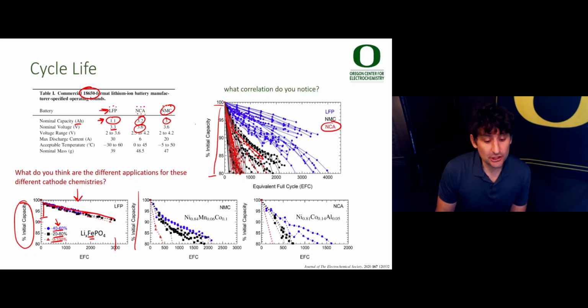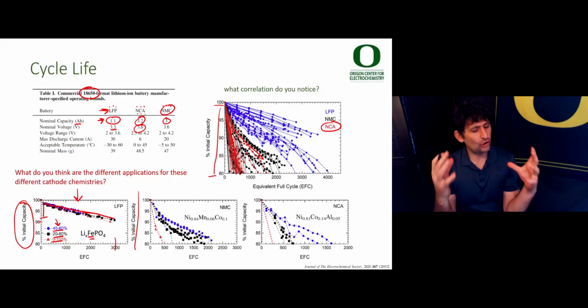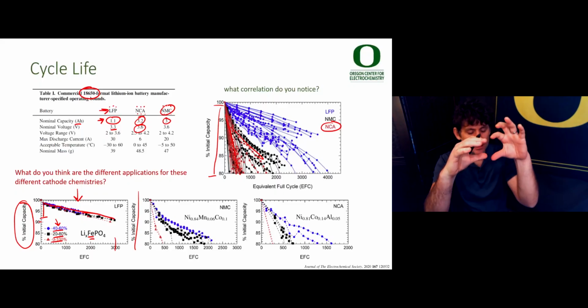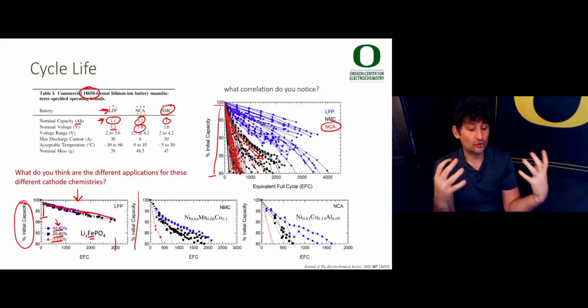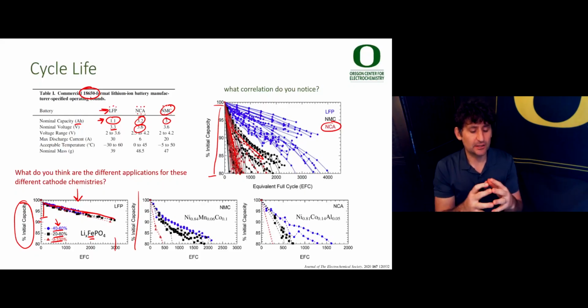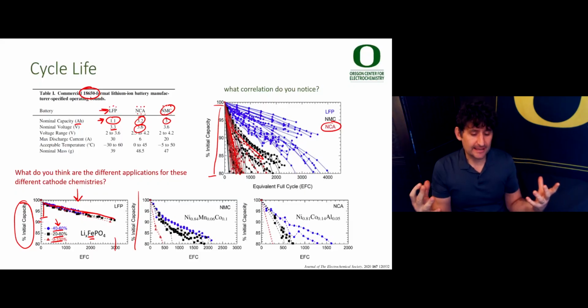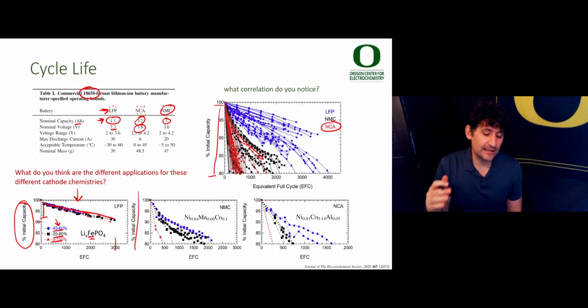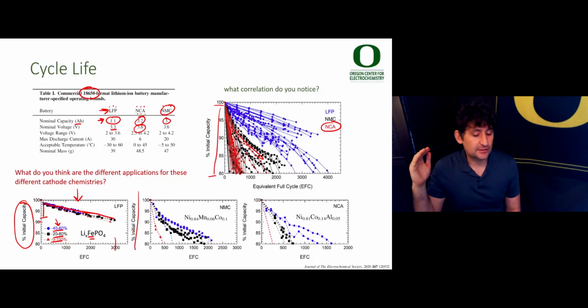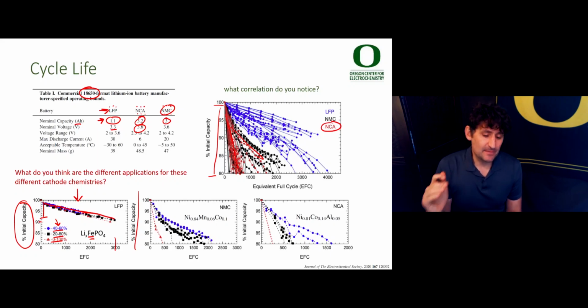So the fundamental challenge in a lot of battery chemistry is understanding how to control all these processes at various length scales, the interfaces, the volume expansion, the formation of SEI layers. We'll talk a little bit more about that soon. So that when the battery cycles, you don't lose capacity, you don't lose voltage, you don't increase self-discharge rate, and you can get these very high capacity batteries to last for thousands and thousands and thousands of cycles. That makes the average cost of putting electrons in and out of a battery dramatically lower if you increase this.